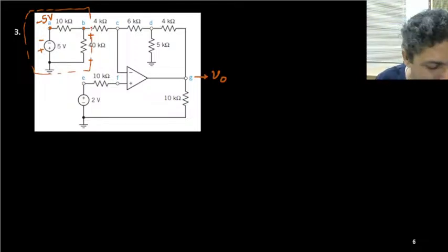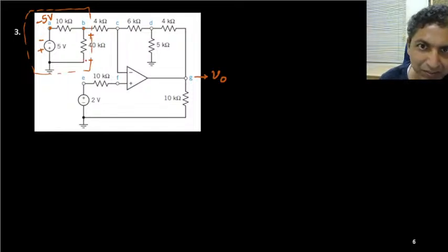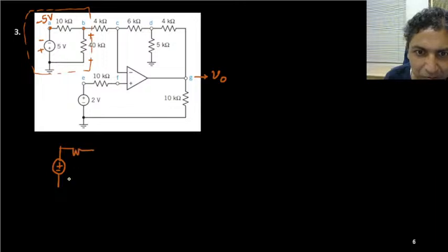Yes, you can do. Here in this you can replace star to delta. You can go for star to delta conversion. Here also you can go for star to delta. That is fine. Then also you can proceed. It's a good idea, but I think there is a simpler way. Can you modify this circuit by one Thevenin voltage source and one Thevenin resistance?